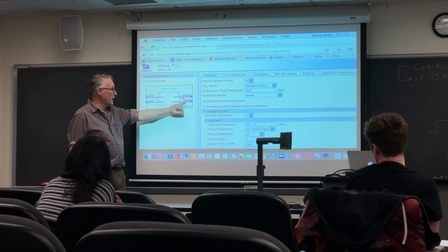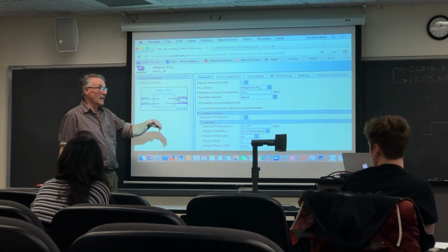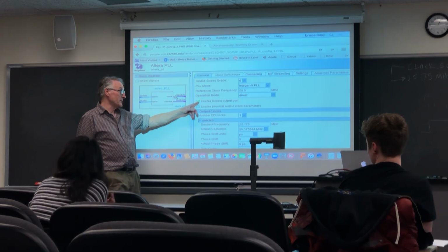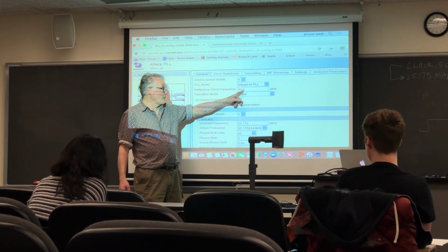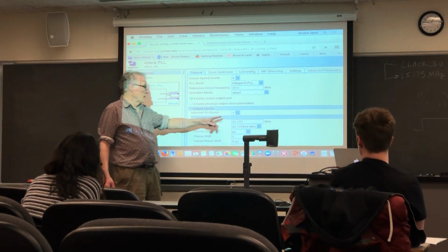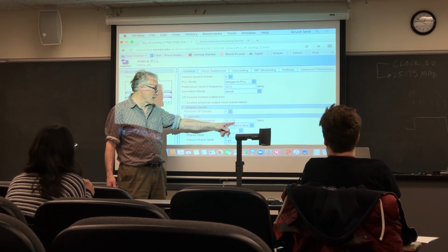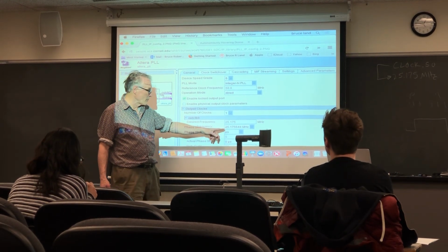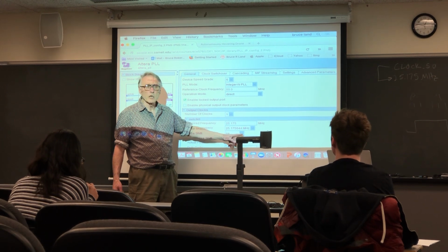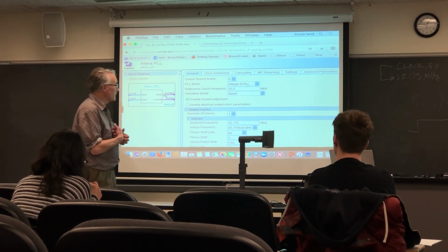There's an output clock, and there is a binary signal that says locked, unlocked, which you can optionally disable. You're going to put in a reference clock at 50 megahertz. You're going to ask for 25.175. The design tool tells you that it can actually generate 25.175644. It's close enough. And you don't want any phase shift.